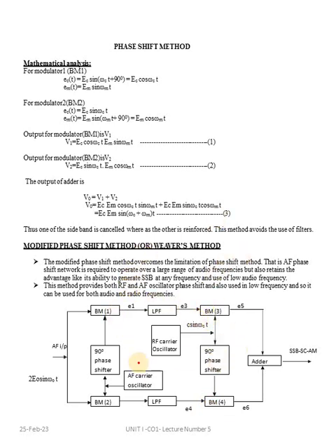So the operation is: the input signal is directly passed through the low pass filter, and then given to another balanced modulator. At the same time, in the second half, the input signal is 90-degree phase shifted, the carrier is also phase shifted, then it is given to the low pass filter, then it reaches BM4. Here also the phase shift is introduced, and finally we sum all these, so the unwanted sideband frequency can be eliminated.